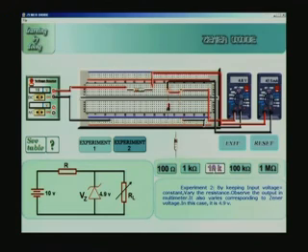So now I move on to another resistor, 10K, and you would find the voltage remains constant, and if I put 100K, still it will be constant, because as I increase the load resistance, the load current will decrease, and therefore the total current will be divided here. Some part will move through the Zener diode and the rest will flow through the load resistance.